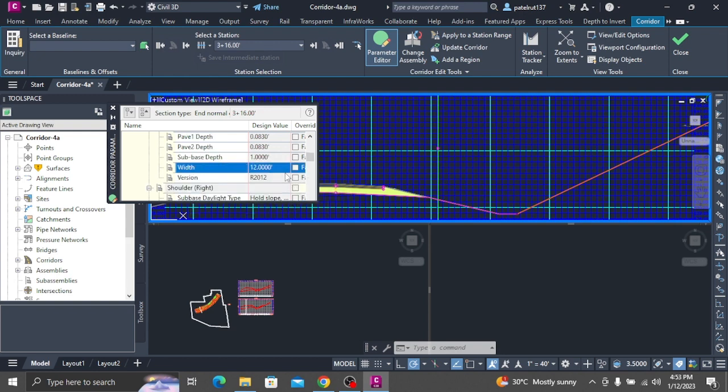Also notice the superelevation transition of the road. At station 4+50.00, the lanes are relatively flat. Note: for more information about superelevation, see the Applying Superelevation to an Alignment tutorial. On the Station Selection panel, in the Select a Station list, select 7+75.00.